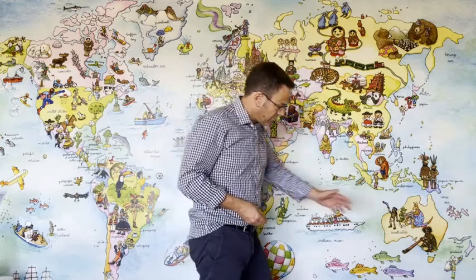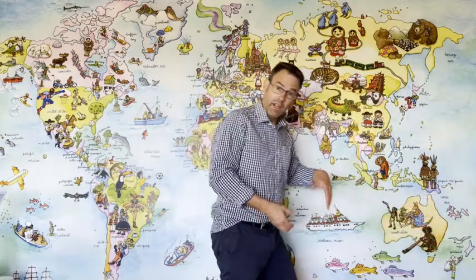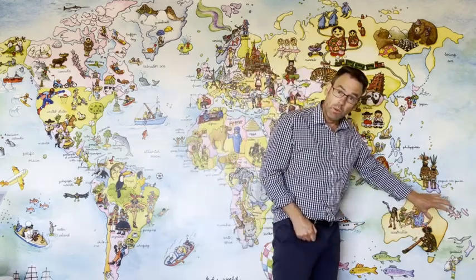Now then you get situations like my home country, which have complicated this even more by trying to do the best of both worlds. Down here in the bottom of the planet, they have a national coordinate grid, not unlike the United Kingdom. They call it New Zealand Map Grid. And they've chosen to adopt over 20 individual projections around the country and the outer islands to try and get the benefits of our very small country projection which minimises that distortion. For those who've worked in Auckland before, you may be familiar with the local example of this. It's called Mount Eden 2000.